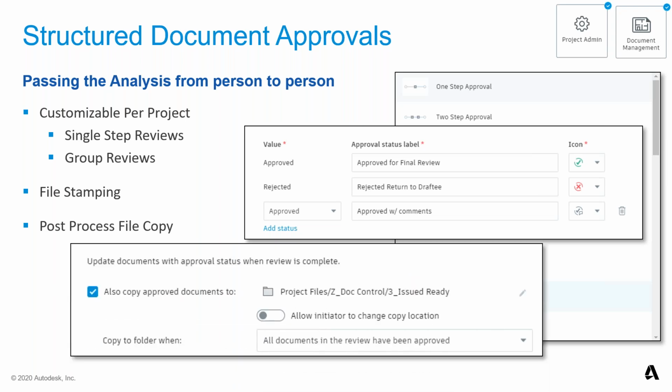Once they are in the coordination space, they can be viewed for clashes, which happen automatically in the background, don't forget, as well as other important design requirements. You may designate various stages of interdisciplinary checks along the way using the approval workflows and model coordination spaces.